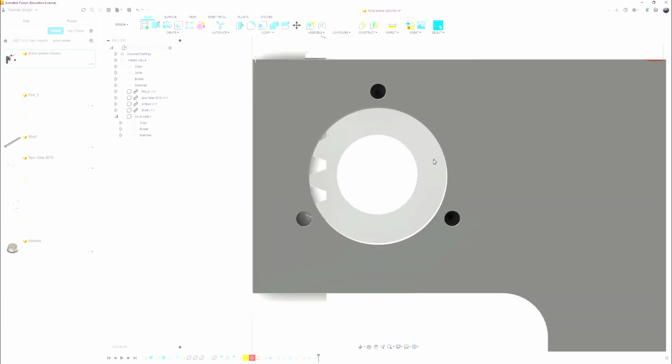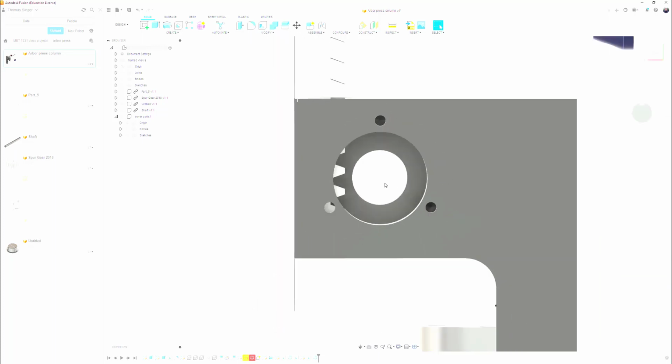So now we've got our 3 holes, we've got our cover plate. We can then use the joint command to align them up, and then we can also now insert our screws into that process. If you're going to insert screws, you'd want to use the insert McMaster-Carr component from the insertion on the ribbon. And again, this happens to be a socket head cap screw 8-32. You'd want to go no more than a 1/2 inch length. And so you're able to pick that up very easily through the McMaster-Carr component environment to develop that screw position.